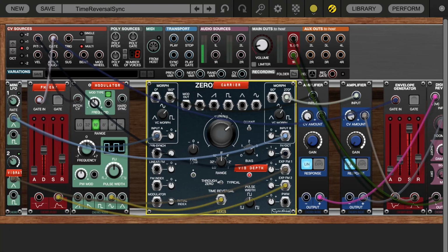Here's another little trick that's pretty much universal to Voltage Modular. Let's say I've got this turned up all the way, 100%, and I'm getting this much sweep. But I want more. What can I do? Well, I could put this through an amplifier or something, but there's an easier way. Remember, every jack in Voltage Modular is really multiple jacks, and those jacks represent a 6-way mixer.